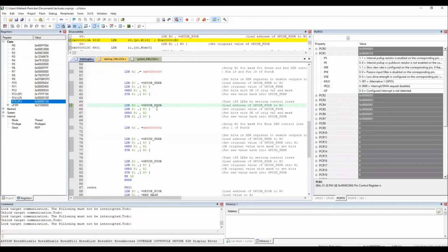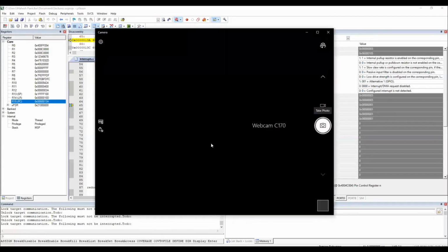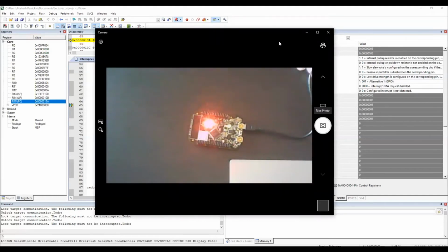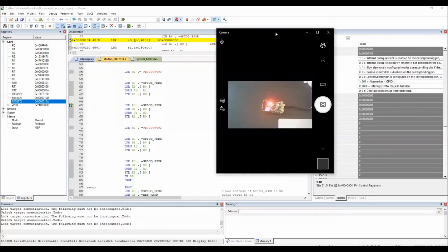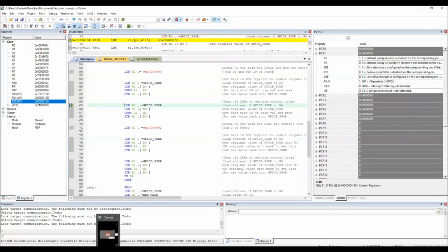And then here I'm actually setting out the. So basically, the next few steps I'm going to do is set the port B's output registers to disable any color. That means all three are set as high, so that at the start, at the initialization part, the LED is not glowing. So you can see here when I start, unfortunately the red LED is glowing. So what I will do is I'll just minimize the screen so that you can see it. Sorry.